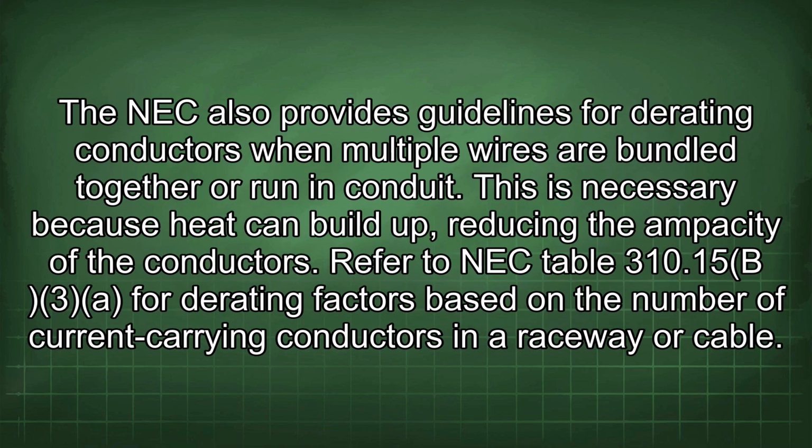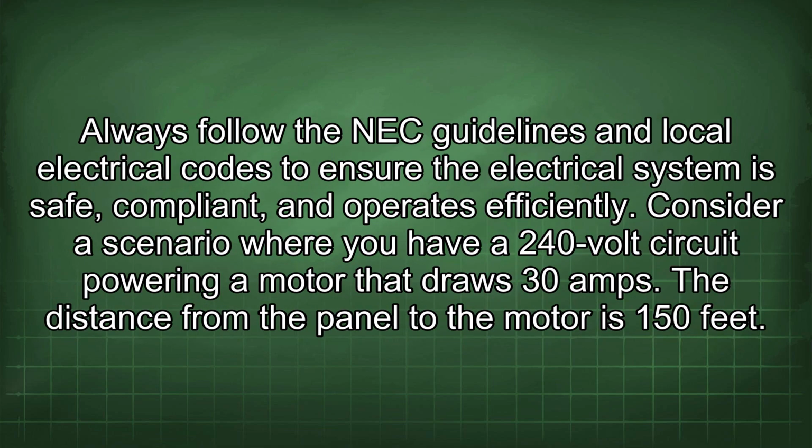The NEC also provides guidelines for derating conductors when multiple wires are bundled together or run in conduit. This is necessary because heat can build up, reducing the ampacity of the conductors. Refer to NEC Table 310.15(B)(3) for derating factors based on the number of current-carrying conductors in a raceway or cable. Always follow the NEC guidelines and local electrical codes to ensure the electrical system is safe, compliant, and operates efficiently.